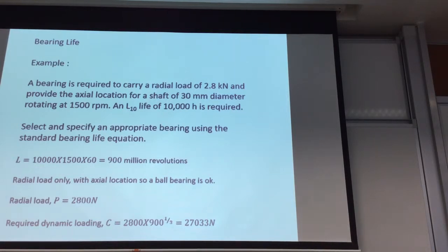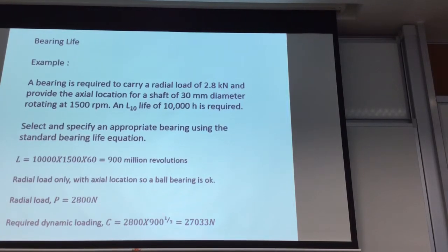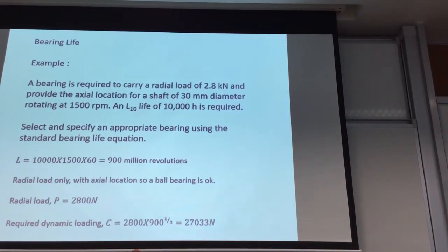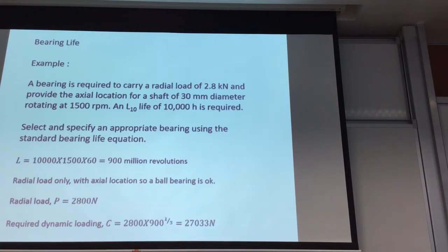The speed you should be aiming for is 2000 RPM because that's the specification. And only the bearings that are connected to your motor should be running at 2000 RPM, because the other bearings, because of your gears, you actually reduce the speed. So only the bearings which are connected to your motor are the ones running at 2000 RPM.